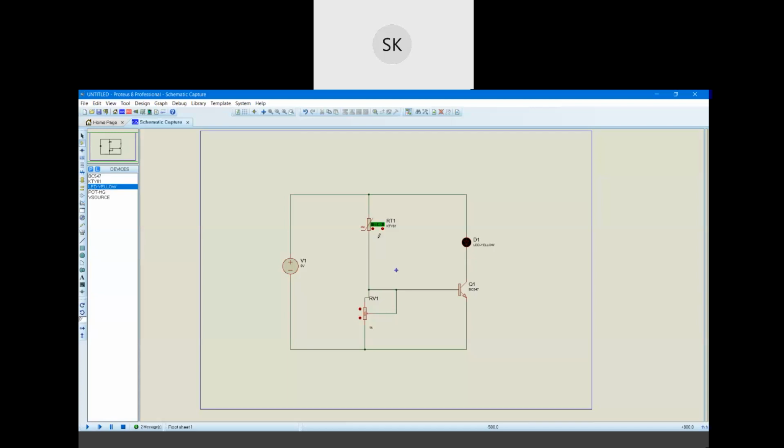Okay, we got one question: how does the thermistor relate with the fire alarm? So we know that fire, like I have told sometimes before, has two characteristics. One characteristic is its temperature and another characteristic is IR radiation, that is infrared radiations. So both those characteristics caught by the sensor can be considered as a fire.